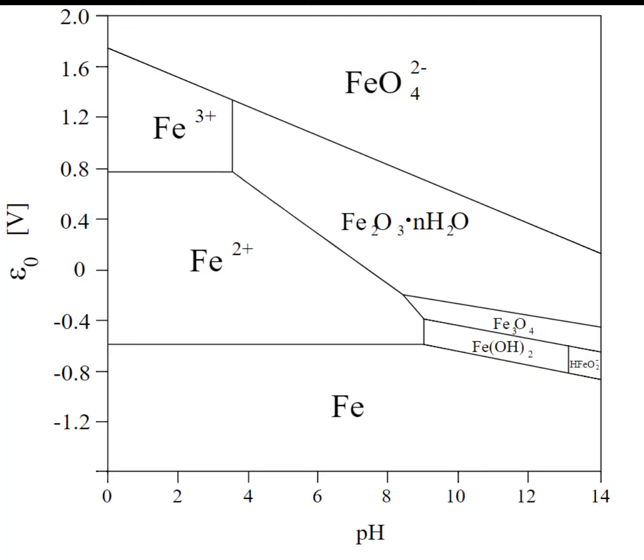So here is the Pourbaix diagram of iron. It's another way of looking at it, and this is what I want to see at this point. We can see if we were at a pH of 7, which is where my weird magnifying glass is. I should really change that, but I'm not entirely sure how to. If we look at this at pH 7 and we go up to here, we can see that if we have a low enough voltage, we can reduce iron to iron 0 and it is thermodynamically stable.